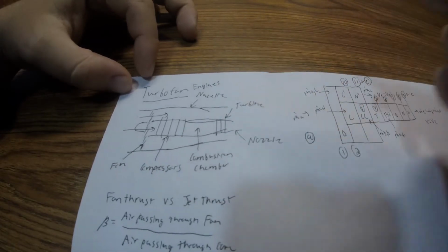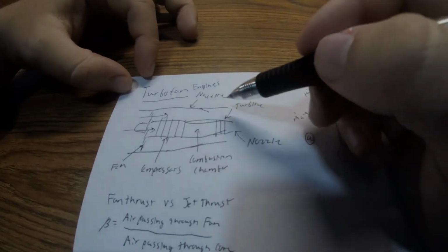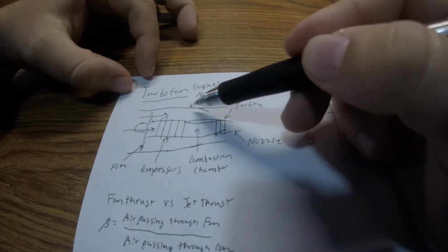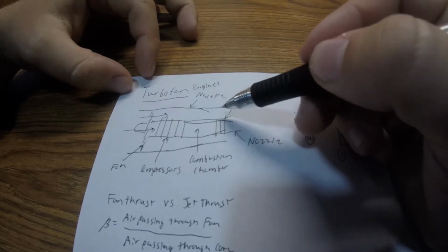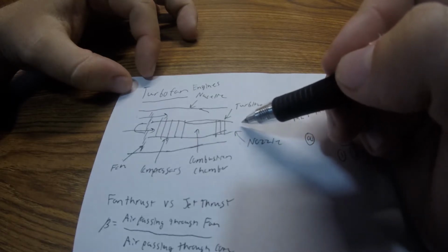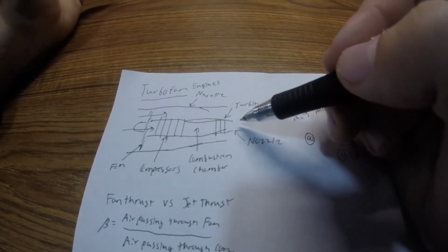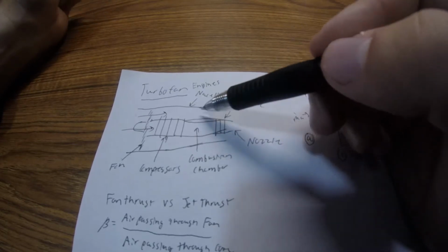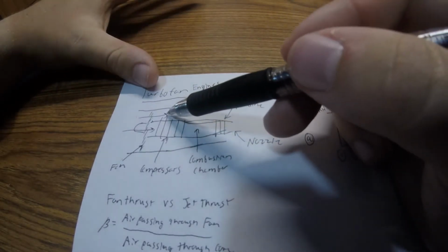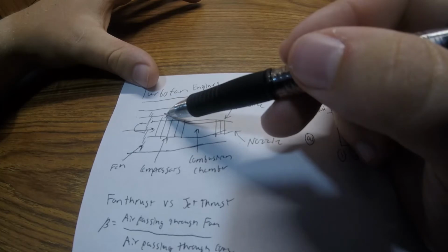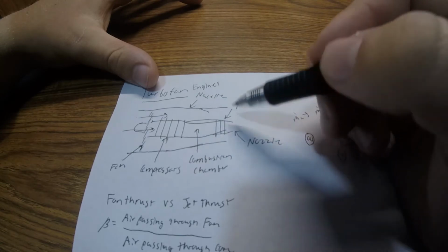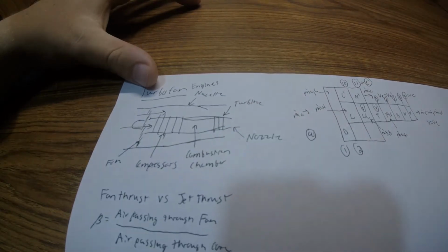Another part of turbofan engines is that sometimes they will mix the exhaust gases coming from both of these, and that lowers the average temperature of the exhaust gas. If you're in a situation where you want a low temperature signature, like in a fighter jet, you can mix the exhaust gases to lower the average temperature, because, and we'll see this when we do a calculation, the exhaust temperature coming out of the fan is going to be a lot lower than what is coming out of the combustion chamber. Theoretically, mixing them does give you more performance.